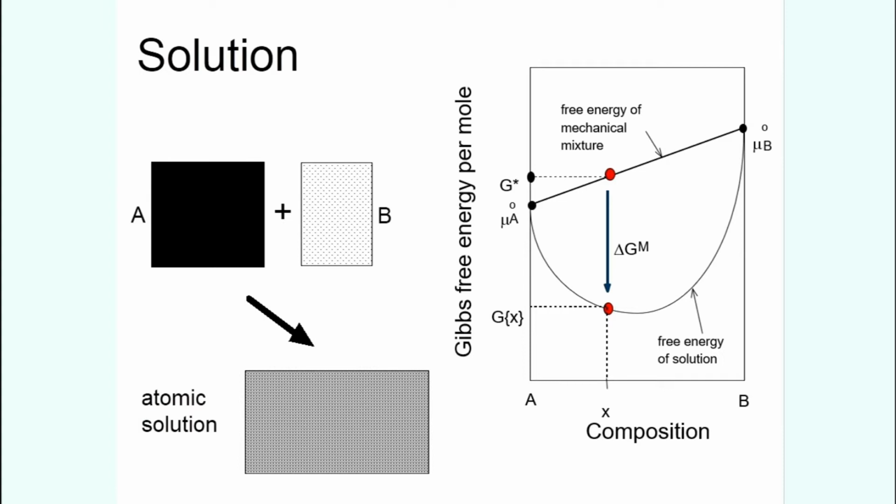Let us give an example of very common steels. Steels have very low carbon, less than about 1 weight percentage. Like in 100 grams, you have less than about a gram of carbon. 100 grams of what? Iron. You have iron as the base material for steels, right? Correct? You know that. So that means you are adding carbon into iron to make a solid solution. Well, steel has many phases like gamma austenite, alpha ferrite, delta ferrite, many solution phases exist. So, solid solution is a very important concept.